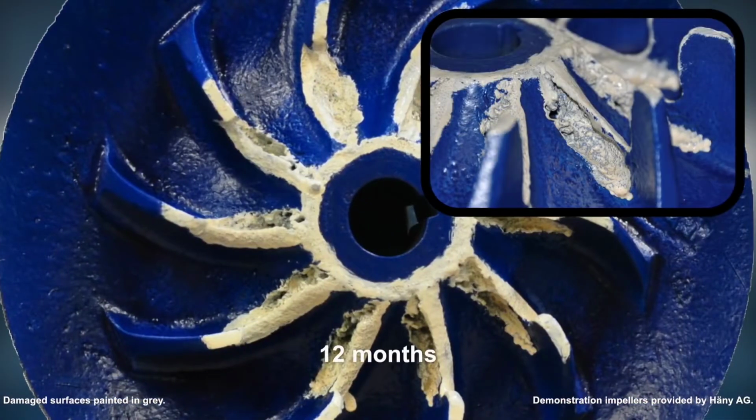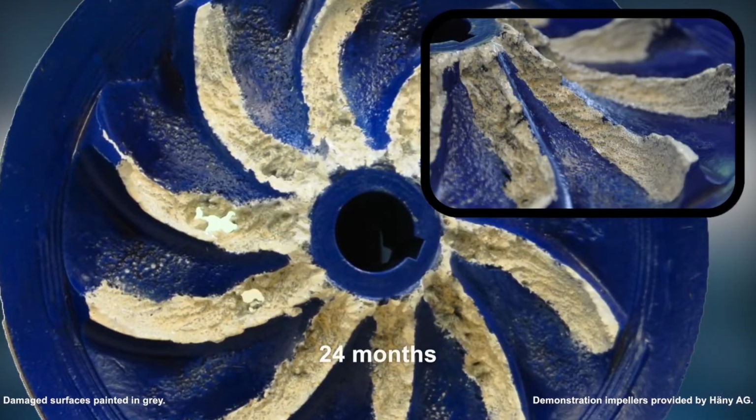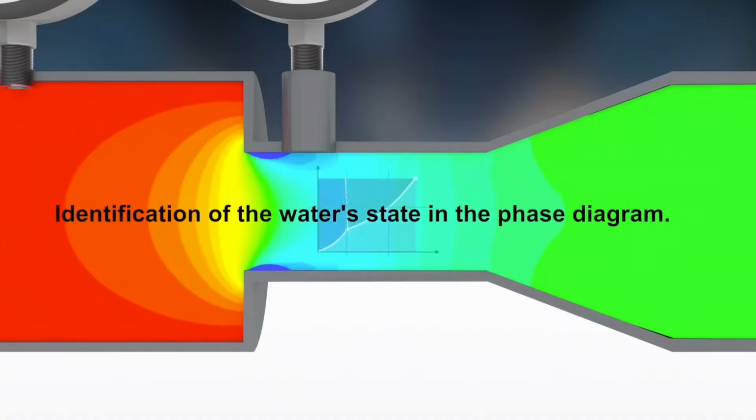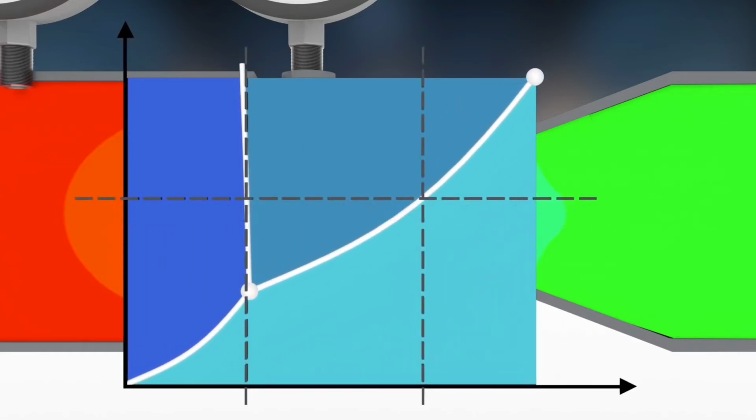After a year of operation under cavitation, the damaged geometry has a different shape and therefore affects the flow patterns, causing material to break off at the top edge of a blade. After 2 years, the blade has been eroded completely, which makes it impossible for the pump to function. So how are cavitation bubbles formed?